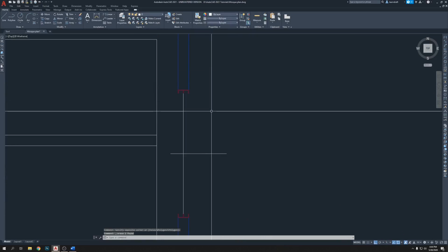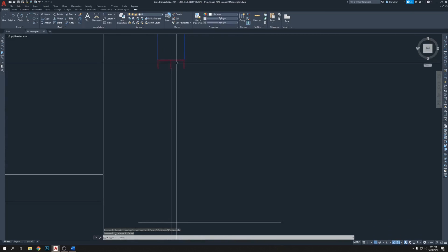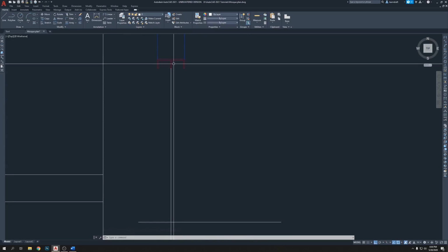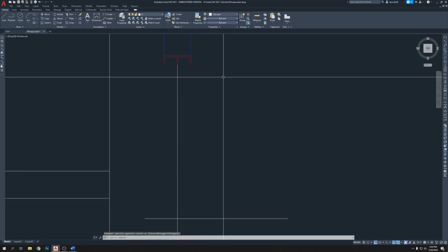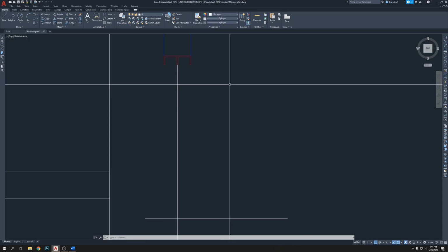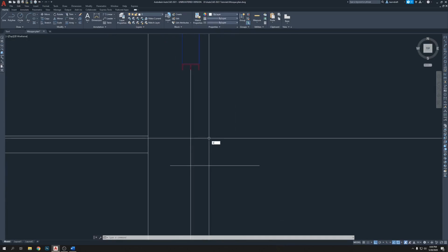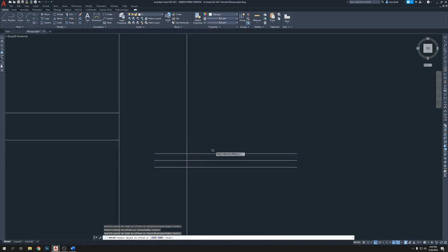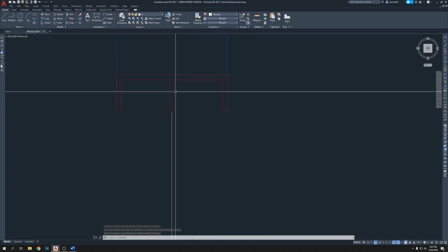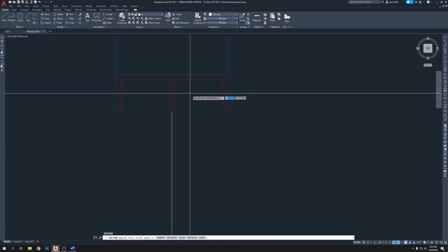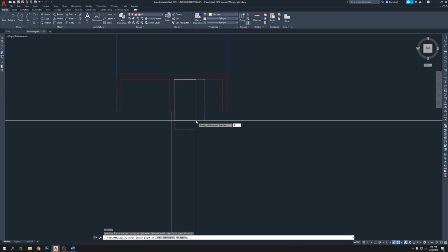Now we're good. So this is going to be 1.75 inch inside, and it's gonna come out 1.75 inch. So let's say this frame going to be at least, let's say 3 inches. So the middle frame gonna be 3 inches. So offset, okay, 1.5 here to there, here to there, and then we're gonna make REC, enter, click D, enter.